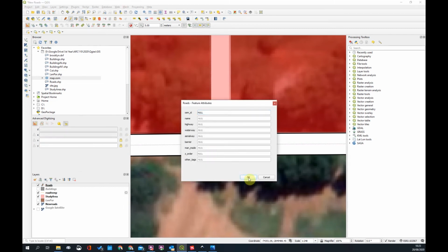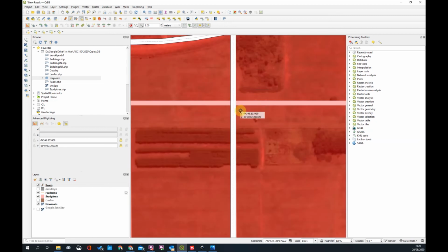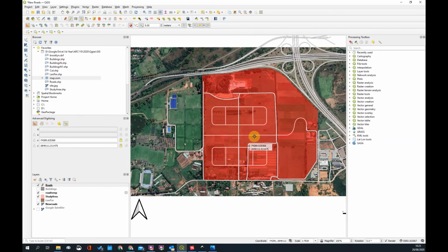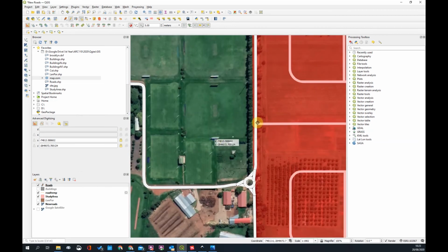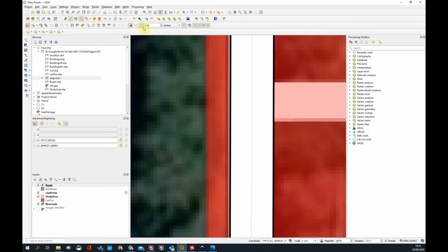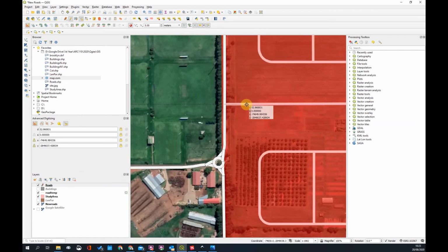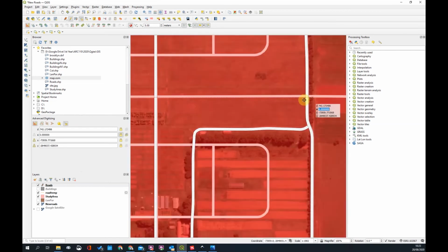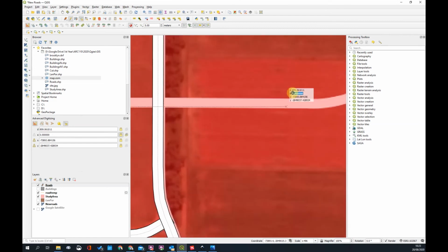Look, it's not 100% accurate, but this will come into play in a minute. So I'm going to start over here somewhere. I'm going to switch off the midpoint. I don't need midpoint for the time being. So I'm going to start anywhere over here. I'm going to lock it horizontal, Ctrl A. I'll pull this road all the way to there maybe. So that's our next road.